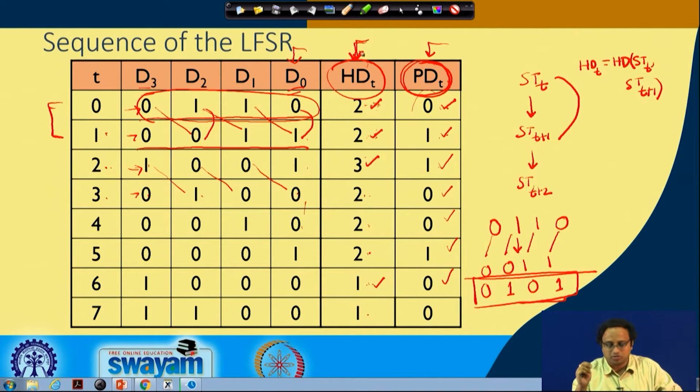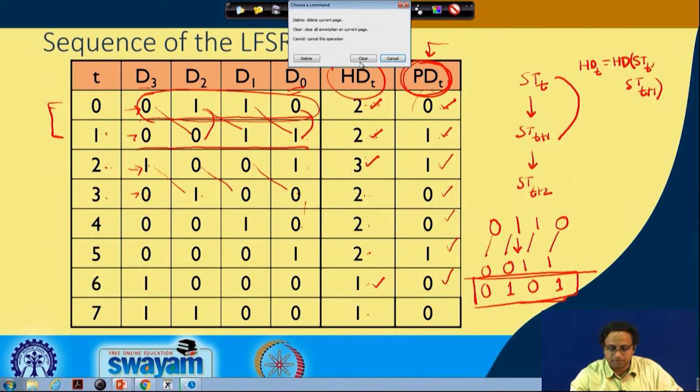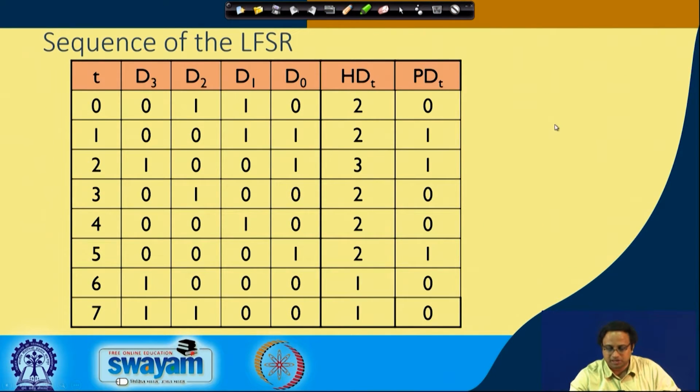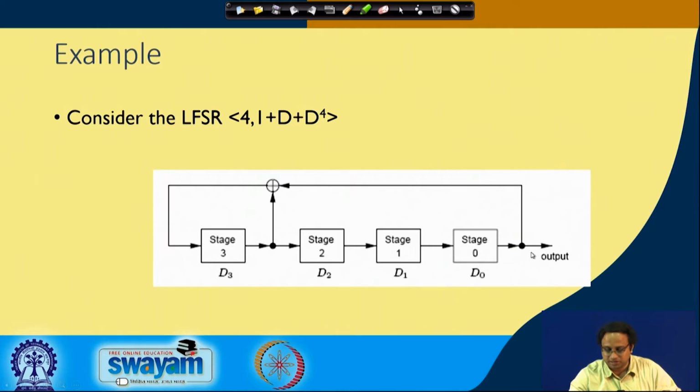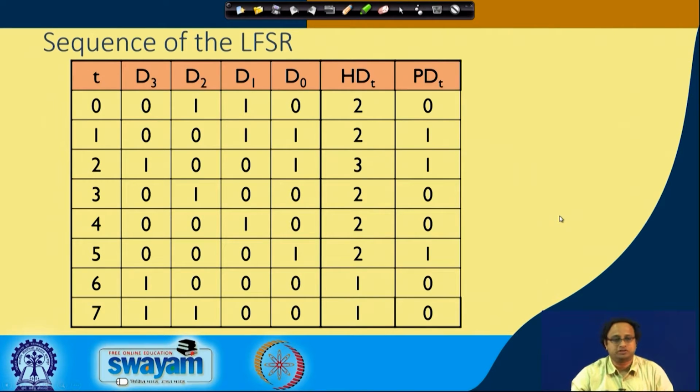Okay. So, now you can probably argue that I already have access to D0, because D0 is the output of my keystream generator. Okay. What I am trying to say is that if I see this diagram, then D0 is the output which I am providing. But note that the attacker may not always have access to D0, because this may be embedded in a big circuit. It may be embedded in a big stream cipher, or at least this point is not always accessible to the adversary. Okay.